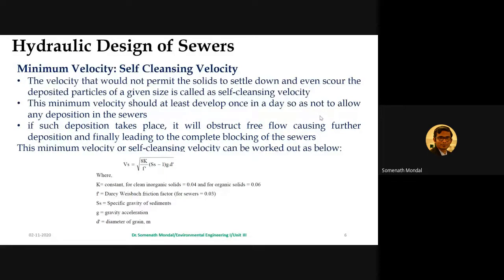So for sewers it is taken as 0.03, and Ss is the specific gravity of the sediments, which is also sometimes denoted as capital G. g is the acceleration due to gravity, and d' is the diameter of the grain in meter.